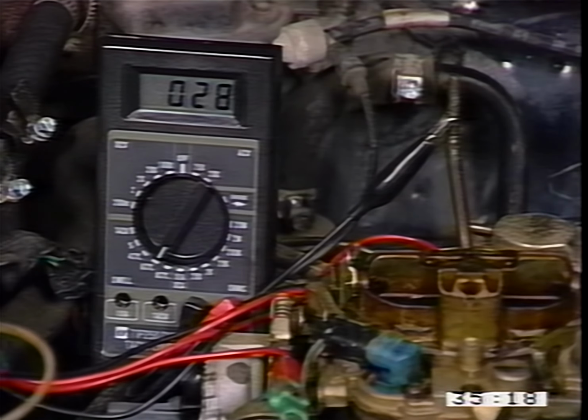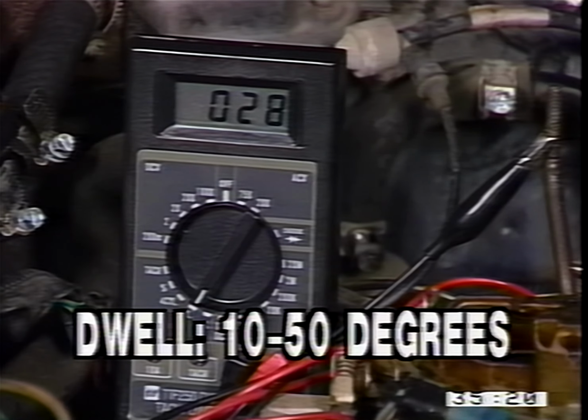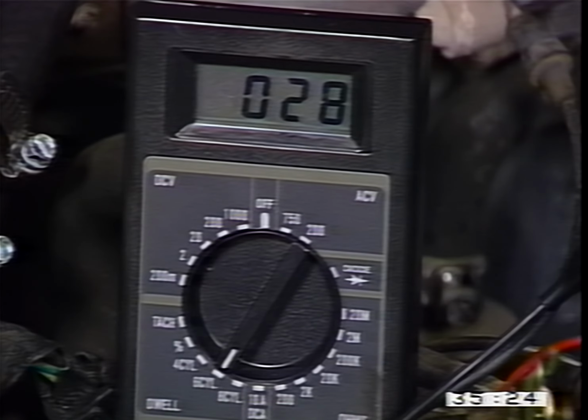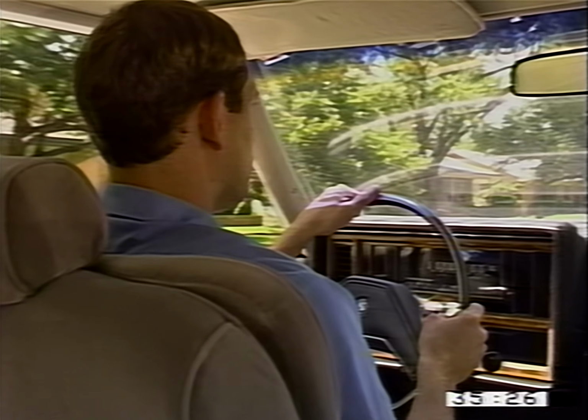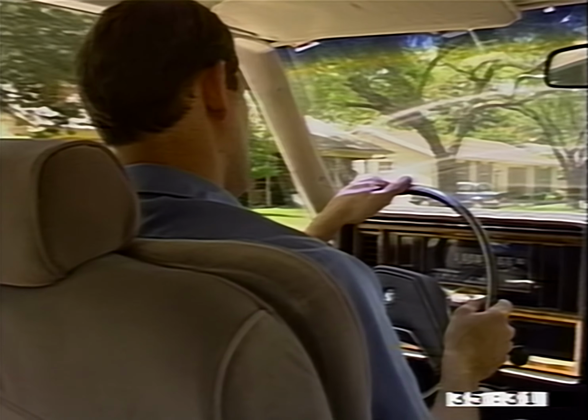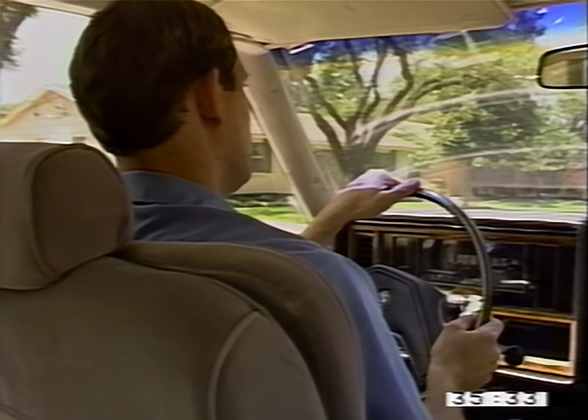Finally, the dwell might fall between 10 and 50 degrees. This signals normal closed-loop operation and requires you to check the air management system. If there is no trouble in the system, long-term memory is cleared and you're directed to check out drivability symptoms.